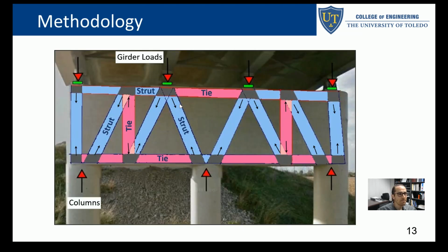So this is just a summary, tension and compression as well. This is another conceptual example. This is a real bridge in Ohio. As you can see, pretty short spans. What is going on? Let's take a look. So I'm seeing, for example, this is a pretty short span and the compression directly goes into the support. But if the span is a little bit larger, you need to use a tie to lift up that stress. For example, this span is larger, maybe around 2-ish, still a deep member. So what you can do is shoot it to such a point, lift it with a tie, which is going to be your straps, and then shoot it again with compression, and that reaches the support. So there's a logic with this.